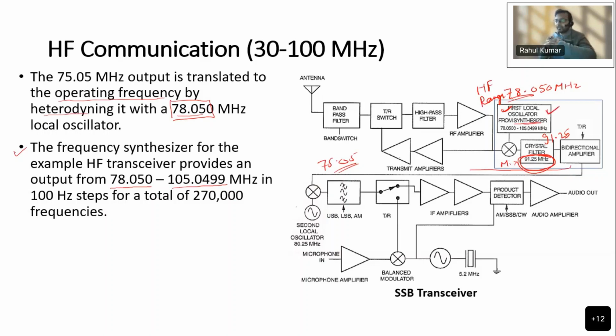This frequency synthesizer block can generate different frequencies within this range, 78 to 105 megahertz, at 100 hertz steps, right?